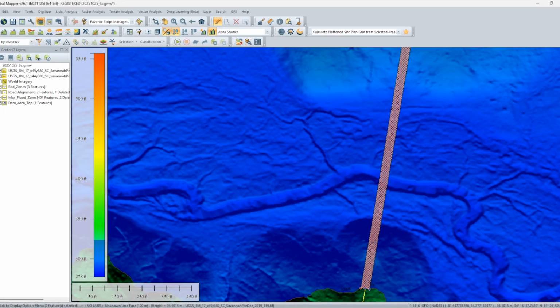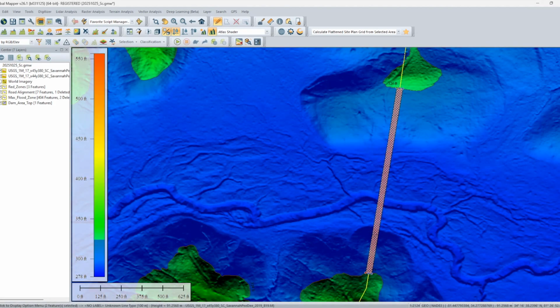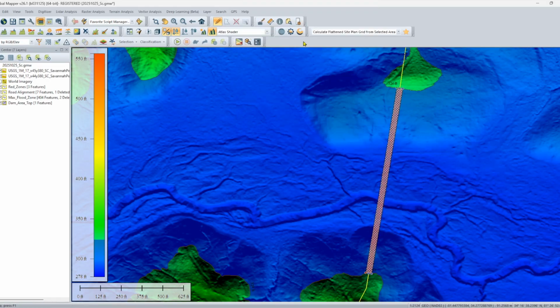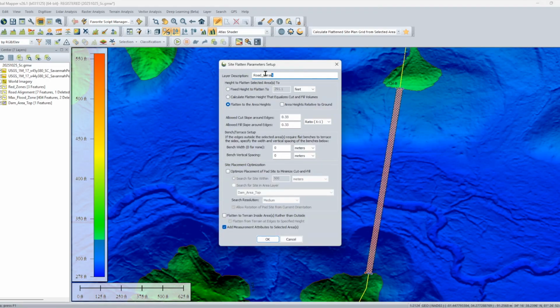All right, now let's turn that buffer into the actual dam terrain. I'm selecting the buffer area we just created, and I'll use the flatten to specific elevation tool to set the top of the dam at 324 feet. That's the same as our maximum water level. Next, I'll define the side slopes. Here I'm entering a slope ratio of 0.33 to 1.